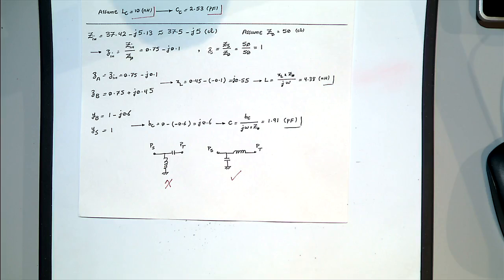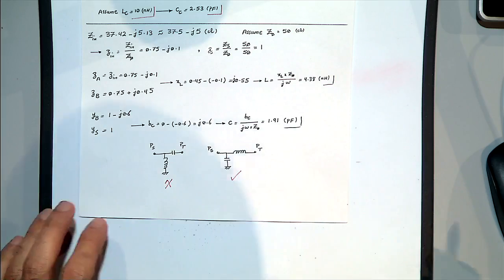If you select the second one, you should make sure that you apply your bias here, I mean move this bias here and then put the second circuit. Else it's wrong, your transistor is not working, because it is not biased. No VB we have here, no IB we have.